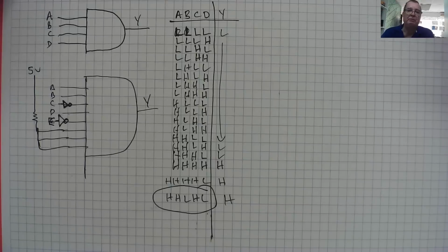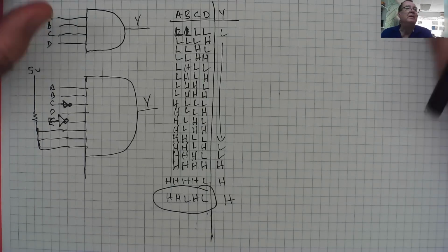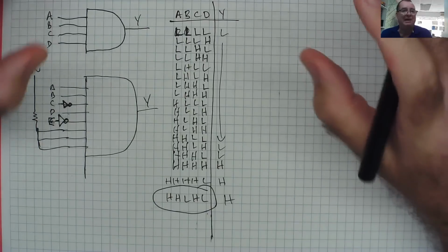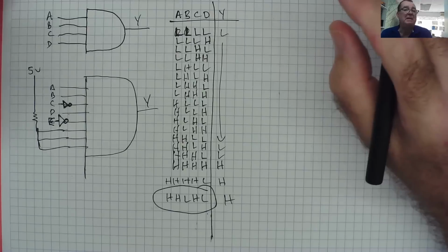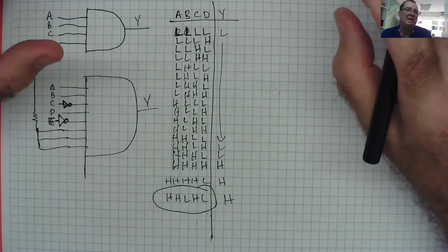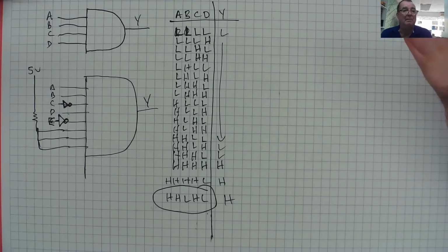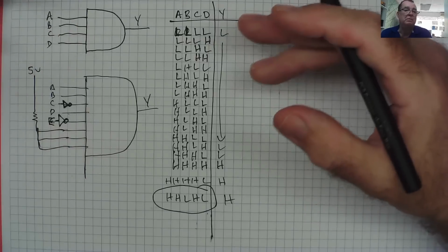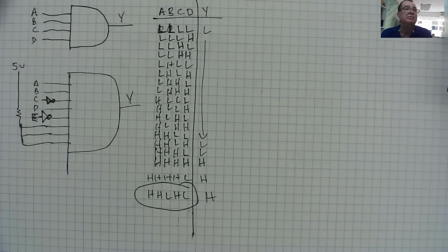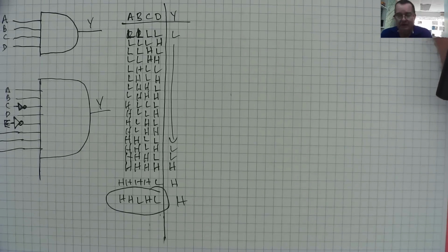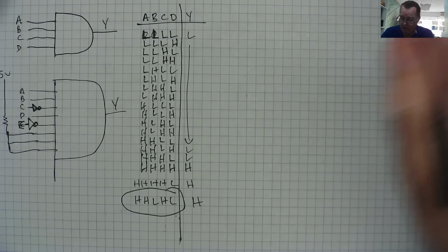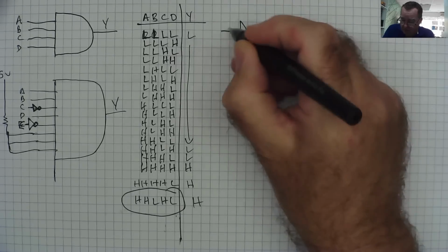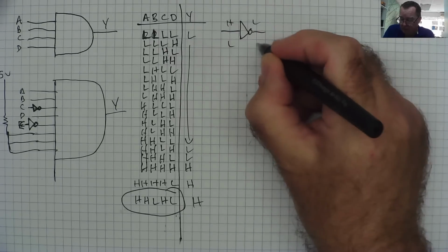And this brings us to something really quite interesting. The only logic gate you ever actually really need is a NAND gate. And the reason being, because you can make every single logic gate from NAND gates. Every single possible logic gate can be made from using several NAND gates. So let me just show you. What if you wanted to make an inverter? Well, you know the truth table: inverter, input is high, output is low, input is low, output is high.